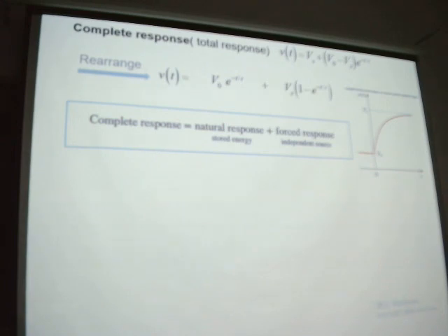So we know why we can use this. It's because of the superposition theorem, right? Because of the superposition theorem, we treat the storage element as a type of source, and the complete response is the storage element working alone plus the independent source working alone. Putting all the responses together, we get the complete response.